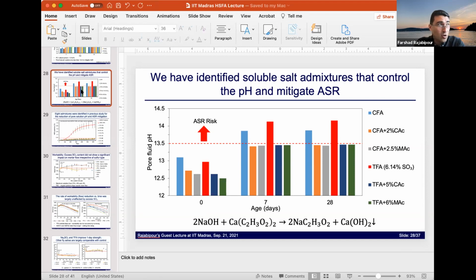We actually started looking at the effect of aluminum or aluminum-bearing compounds. A few years ago, we were looking at aluminum hydroxide as a potential solution, and it does actually work, albeit at significant dosages. You have to replace about 20% of your Portland cement with aluminum hydroxide, and preferably with an amorphous form of aluminum hydroxide to do that.